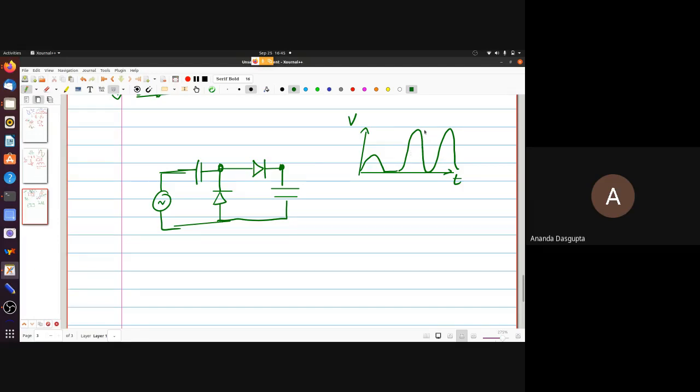Then what do I expect the output of this thing to be? Well, if it's really a peak detector, it should go like this, right? It should essentially go like this, then flat, then this, then holds flat at 2 Vp. Okay, you get my point.